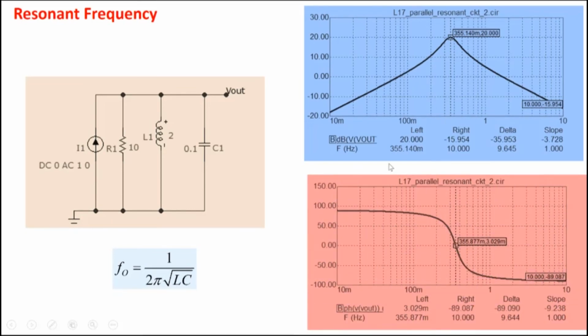Not only that, we have also been saying that at this value, the reactance due to the inductance is equal but opposite in sign to the reactance due to the capacitance. And so the two of them cancel each other, and effectively L and C act like an open circuit. Then you are left with only resistance in the circuit, and thereby the current and the voltage are in phase. So at resonance we also get zero phase.